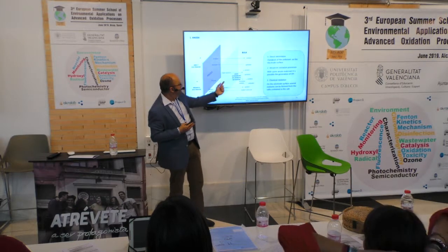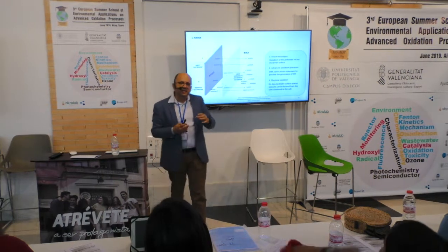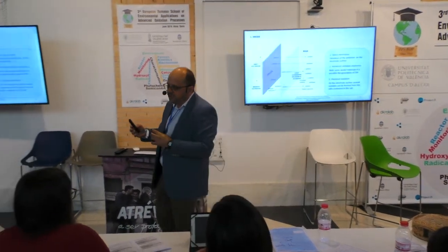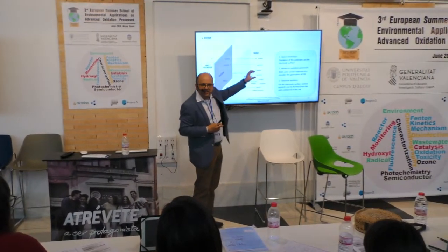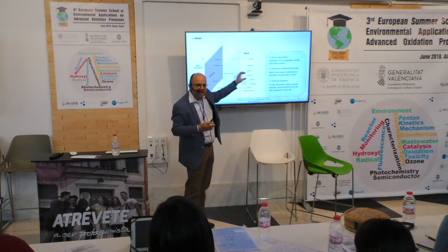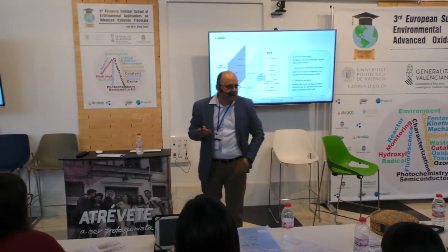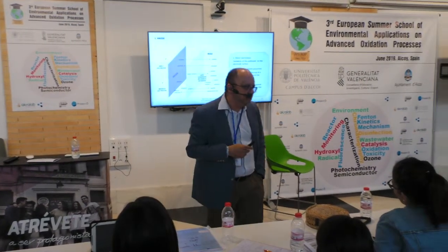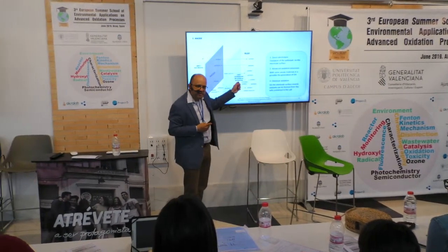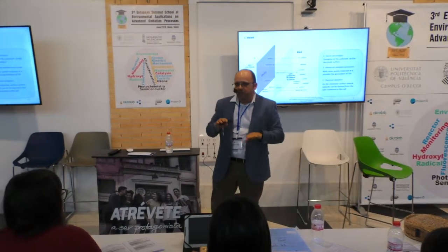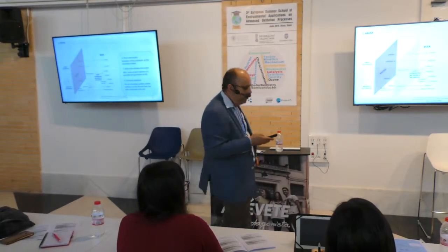In addition, we can produce oxidants on the anode, and these oxidants can attack the organic matter next to the anode, or they can attack the organic matter in the bulk. And we can activate these oxidants using different technologies, such as light irradiation, ultrasound application, or chemical activation. Okay? So if we are clever, we can have very efficient processes by combining technologies inside our electrochemical cell.